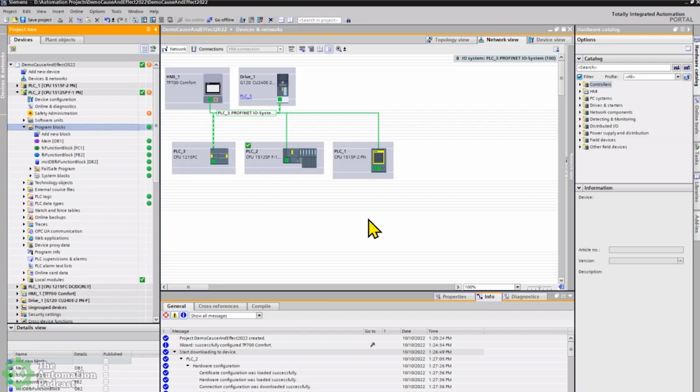Yeah, I agree with what you just mentioned there, Sean, about making it easier for the process guy looking at the PLC and getting into more of a graphical representation of something that means more to them than translating it into ladder logic, especially if you look at the workforce and the programmers today doing more in scripting languages or locking down blocks that are more standard. The cause and effect matrix does give us the opportunity to make transparent some of the control code or status of a certain situation in a nice graphical editor that's actually controlling the process in the PLC.